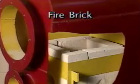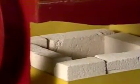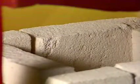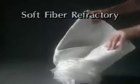There are two types of materials commonly used for combustion chamber refractories. Fire brick has been used from the early days of oil combustion. The bricks, or hard-cast chamber surfaces, provide refractory that is durable and can operate in the 2300 degree Fahrenheit temperature range. The second material is a soft refractory material typically made of alumina silica fibers. This material has an operating range to 2300 degrees Fahrenheit.